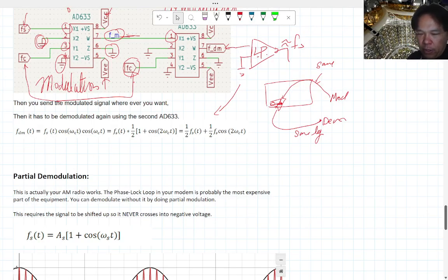But why do we have to have this? Why do we use partial modulation on AM/FM radios? So AM radio, since we're doing amplitude modulation, that's what the AM stands for. Remember that in order for the modulation to work properly, you need a multiplier on one end with a carrier frequency, and you need a demodulating multiplier on the other end with exactly the same frequency.